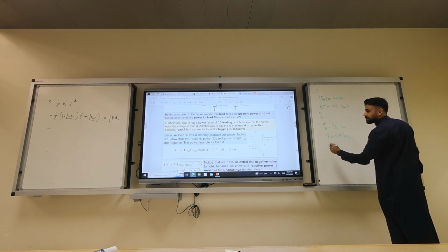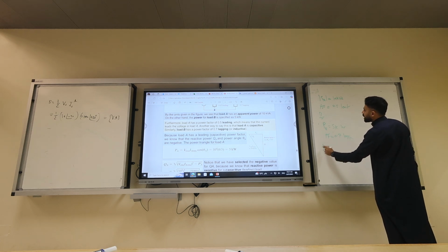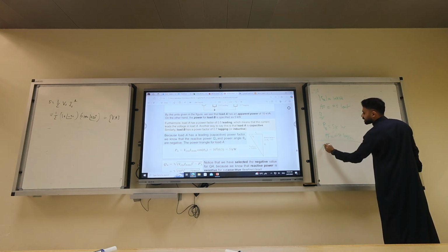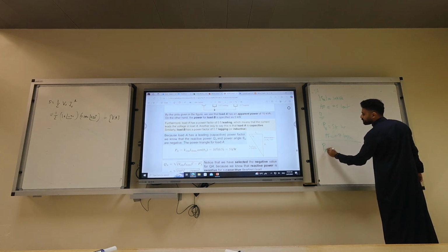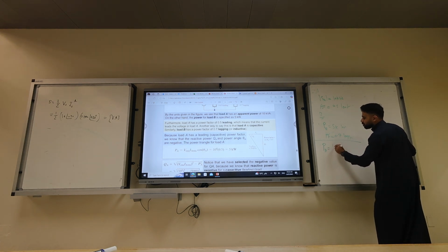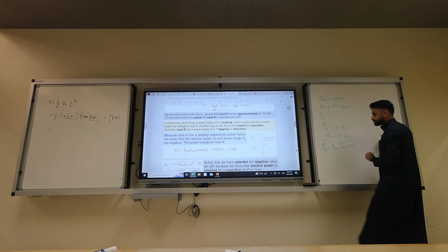I already know S, so now it's time to calculate P sub A. The P is what? V RMS times I RMS times cosine of theta, right?